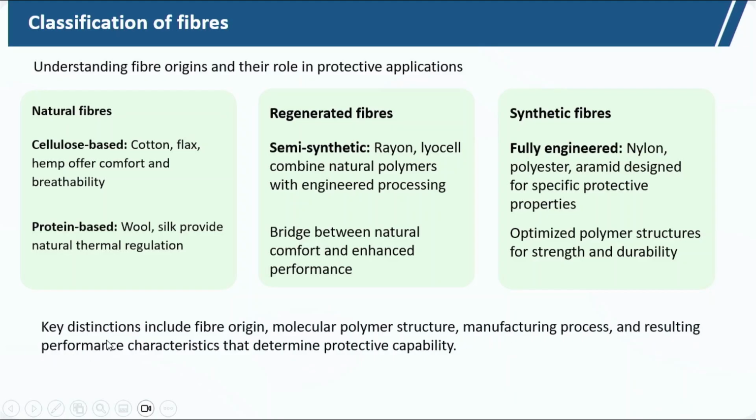So, key distinctions include fiber origin, molecular polymer structure, manufacturing process and resulting performance characteristics that determine the protective capability. So, that means that you have to select fiber based on the requirement. Okay.